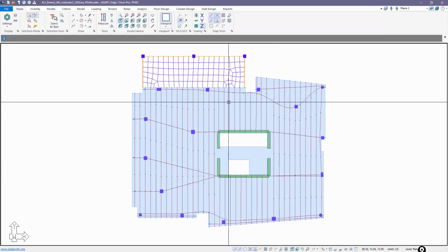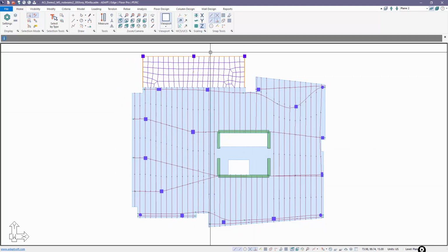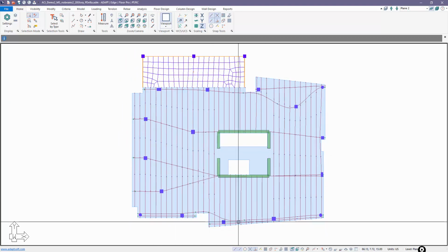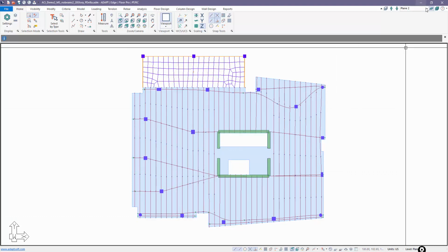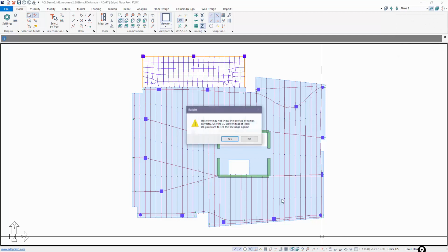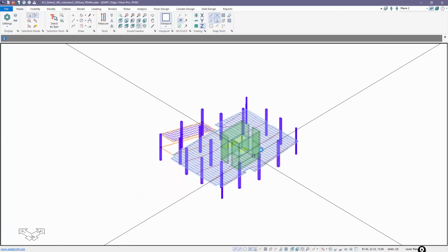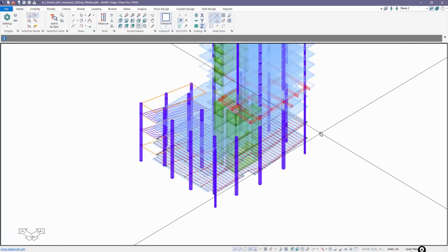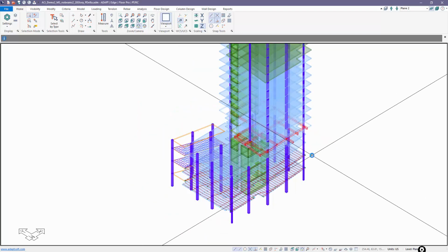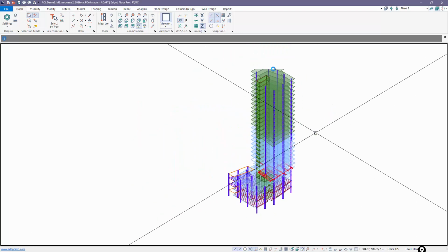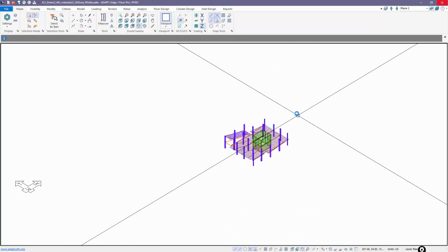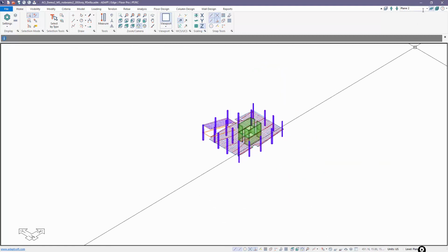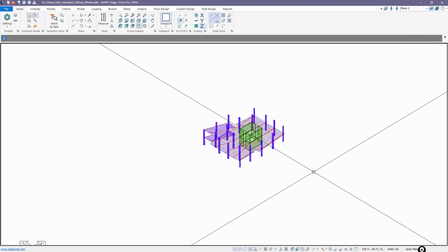This file has post-tensioning in it, and there's some ramping at the top. We're going to largely ignore that. We're going to mainly work here in the model space in what we call single level mode. So we've switched to single level. If I go to a 3D view of this particular model, you can see this actually has several different floors, but we're going to just limit it to single level use. So we'll come back and we're going to work on plane 3.